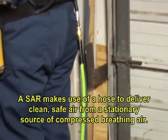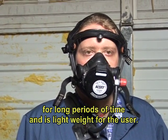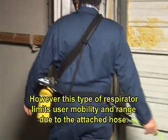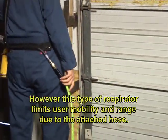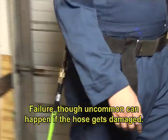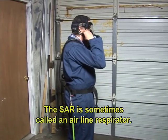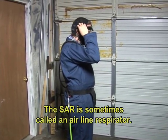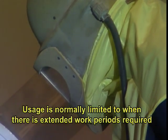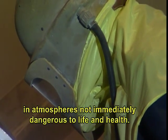The supplied air respirator provides clean breathing air for long periods of time and is lightweight for the user. However, this type of respirator limits user mobility and range due to the attached hose. Failure, though uncommon, can happen if the hose gets damaged. The SAR is sometimes called an airline respirator. Usage is normally limited to when there are extended work periods required in atmospheres not immediately dangerous to life and health.